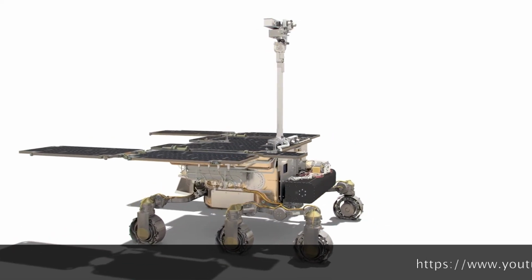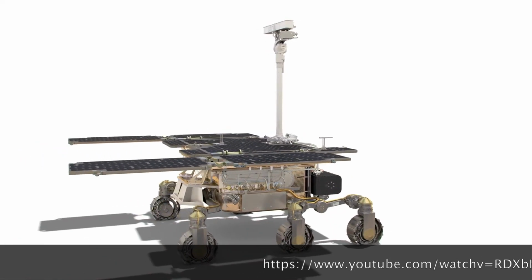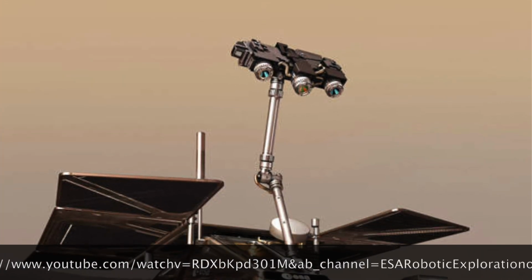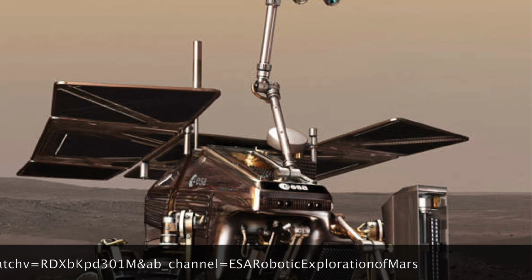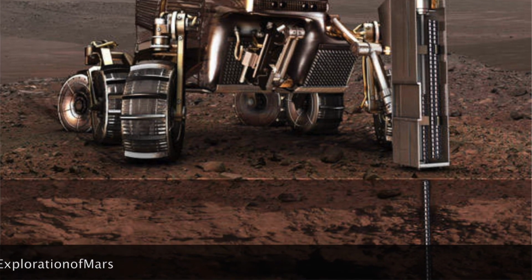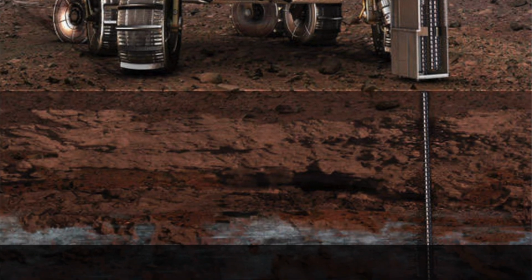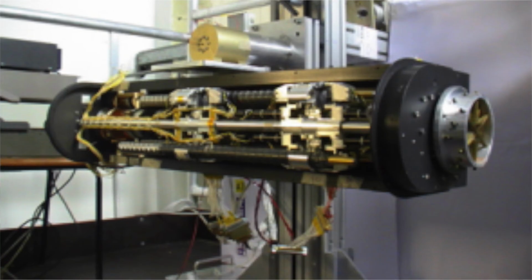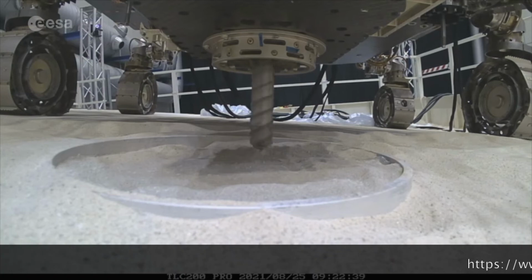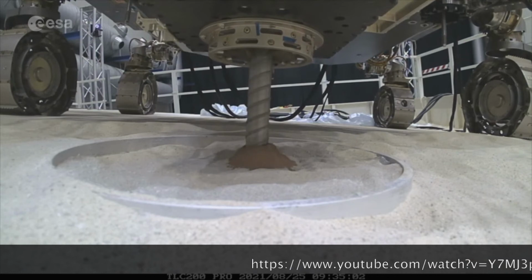The ExoMars mission also makes use of a subsurface drill that is in turn based on the D3. The depth requirements for this drill were set to 2 meters below the ground, where it will recover rock samples. The drill diameter is 25 millimeters. The soil samples will be 40 millimeters in length and 10 millimeters in diameter. To reach the designated depth of 2 meters, 3 extension rods of 575 millimeters have to be assembled onto the drill to form a string that is long enough to reach 2 meters below the ground.